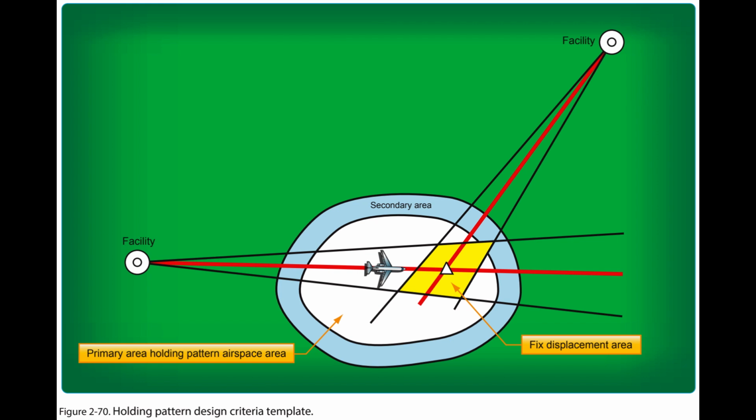Figure 2.70. There are many factors that affect aircraft during holding maneuvers, including navigational aid, ground and airborne tolerance, effective wind, flight procedures, application of ATC, outbound leg length, maximum holding airspeeds, fix to nav aid distance, DME slant range effect, holding airspace size, and altitude holding levels.